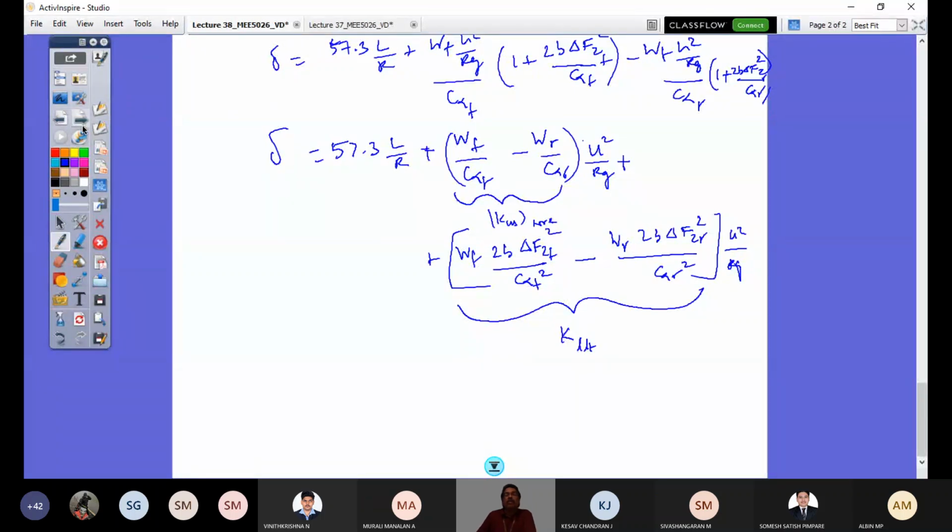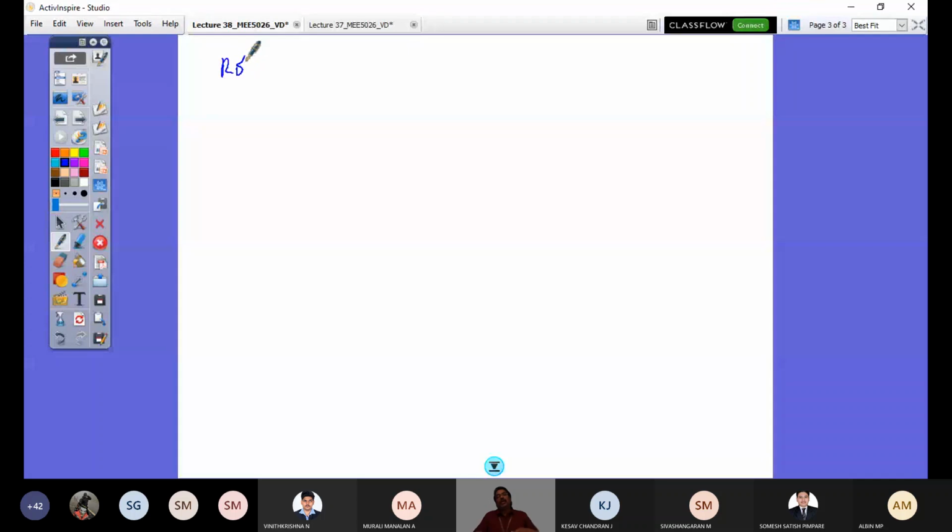So rollover stability, when you say, it is like yaw stability. Yaw stability is there is no understeer effect in your vehicle at critical speed. So if your vehicle has got an oversteer effect, and your vehicle is at critical speed, you know what would happen. Your vehicle will spin about a vertical axis arbitrarily. So that is the unstable state and yaw motion that we have seen. For that to understand, bicycle model is sufficient.